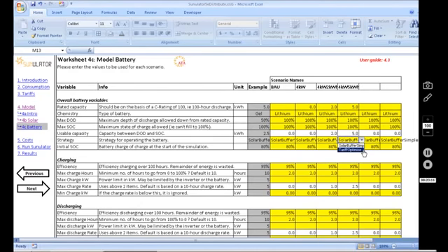So it's making that decision and then saying, okay, today we're going to pre-charge 3 kilowatt hours from the grid, for example, and it'll spread that out over the morning off-peak period. So that might be from midnight to 7 a.m. in the morning, for example.